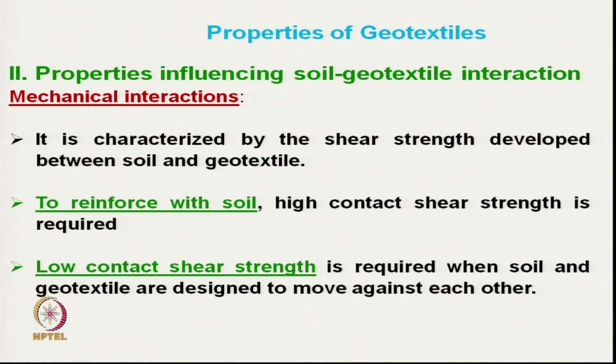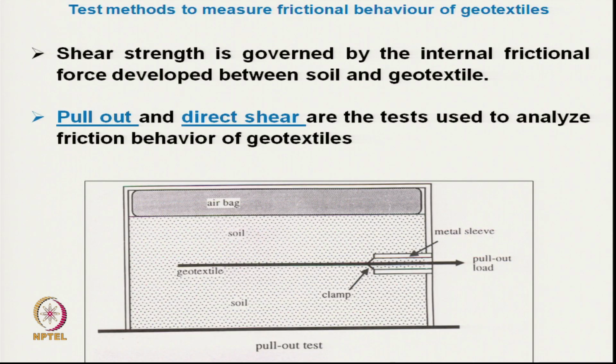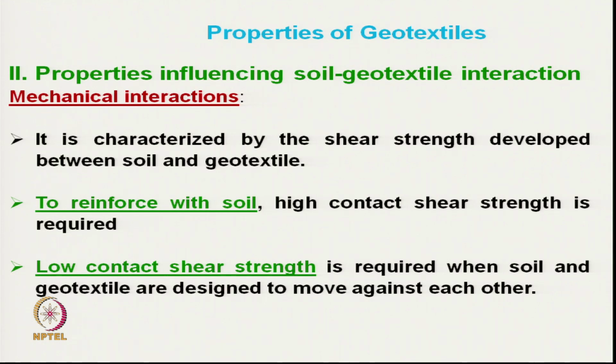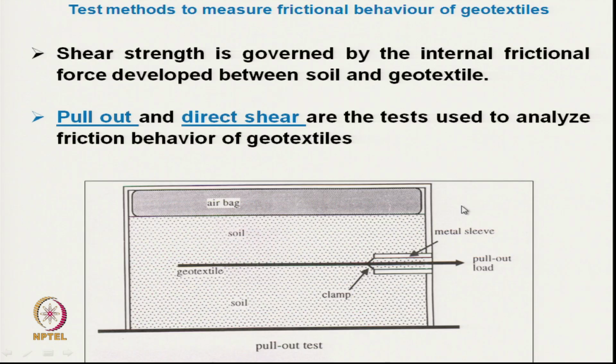This interface mechanical interaction between soil and geotextile can be assessed by shear strength. The shear strength is governed by internal frictional force developed between soil and geotextile,